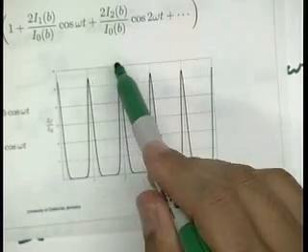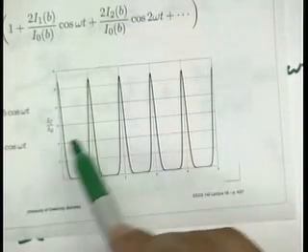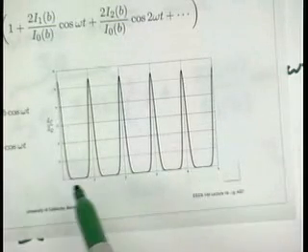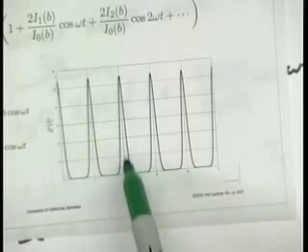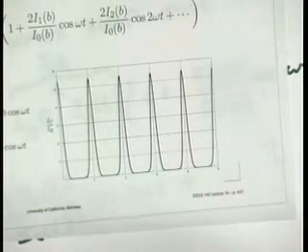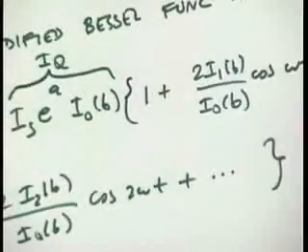When it's positive, the current shoots up, right? This is IC divided by IQ. So you can see that the collector current is 5 times larger than its bias, which is at 1. And then when the VBE goes negative, the current essentially goes to 0. The device shuts off. So as a function of B, I can plot this a little more carefully.